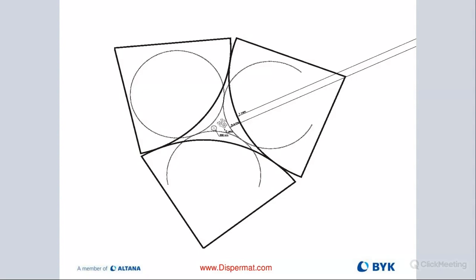I really like this slide because it shows what is actually happening in the mill as we are milling. On the left, you can see the bigger particle. It's kind of like an aggregate. Then as these beads collide, it gets pushed away in those corners right there. That's where the shear force is getting built up. Then that particle gets pushed away, and that will reduce the particle size. So that's what we're showing here. The more often you do it, the further you reduce the particle size.